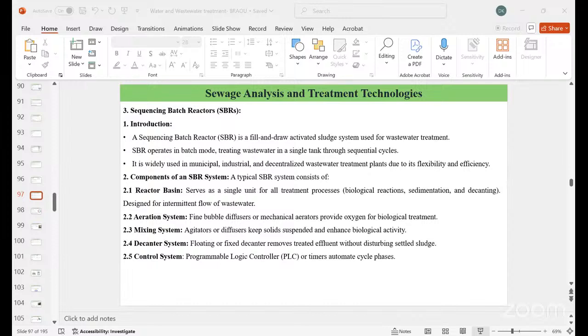So coming to the UV process, all right, ultraviolet and hydrogen peroxide. This combination of both UV light and hydrogen peroxide enhances the production of radicals, and this is mainly by the photo-Fenton reagent, which generates the radicals.